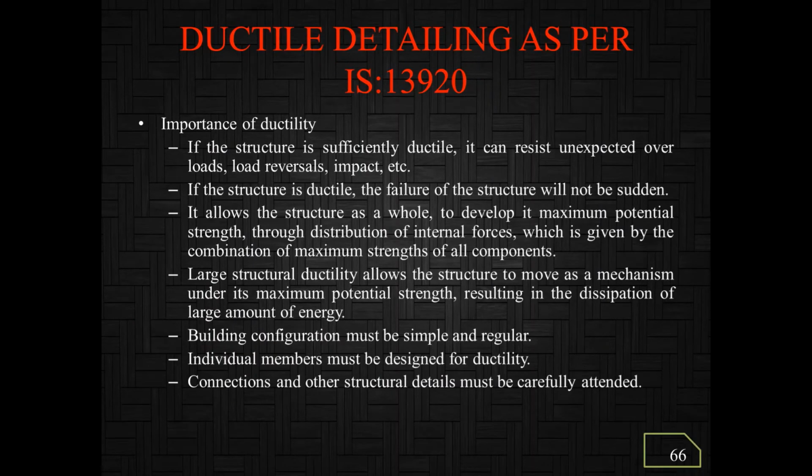Now ductile detailing as per IS 13920. First, why is ductility important? Ductility means if a structure is sufficiently ductile, it can resist unexpected load reversal, impact, etc. This type of detailing is used to resist earthquake force. Providing extra reinforcement to resist earthquake force is called ductile detailing.